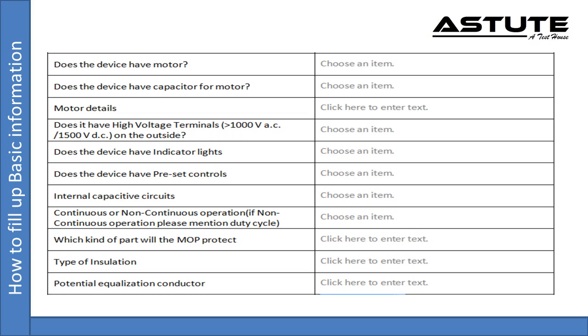Basic insulation. Insulation providing basic protection against electric shock. Double insulation. Insulation comprising both basic insulation and supplementary insulation. Reinforced insulation. Single insulation system that provides two means of protection. Supplementary insulation. Independent insulation applied in addition to basic insulation in order to provide protection against electric shock in the event of a failure of basic insulation.